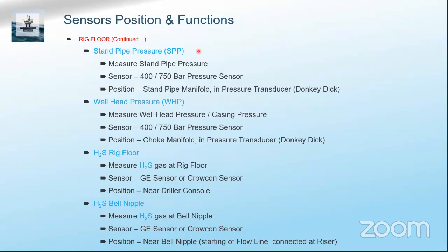That's very important. Most of the sensors come with the manufacturer's unit, and most of these sensors are now 4 to 20 milliamps. The new ones are coming like 4 to 20 milliamps. I think most of the companies are using that, including the drilling crew, if I'm not mistaken. So it's very easy. The manufacturer's calibration is there, but you need to cross check it. The loggers have to check it.